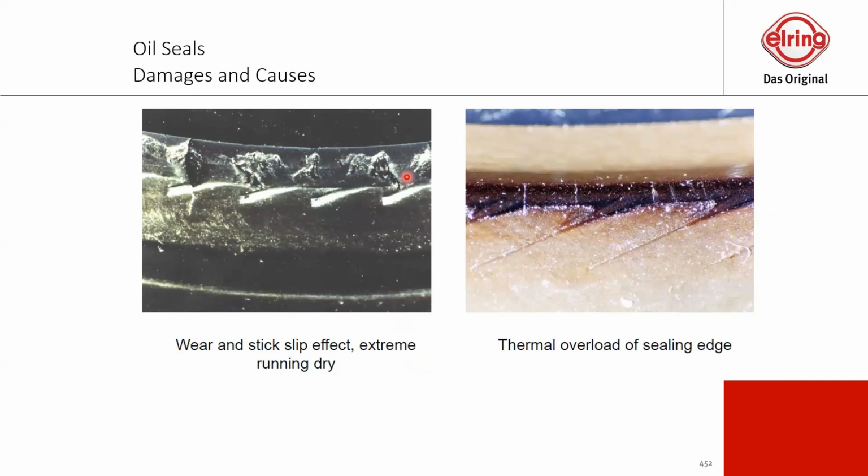For a classical oil seal, also known as Simmerring, you need lubrication. A thin motor oil is the right one. Why thin? I will show you later. So this is essential in the beginning when you install a new oil seal.